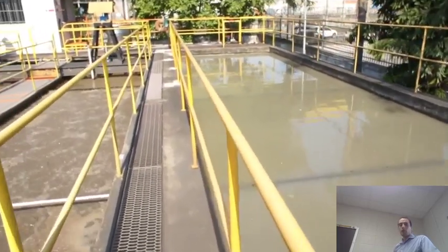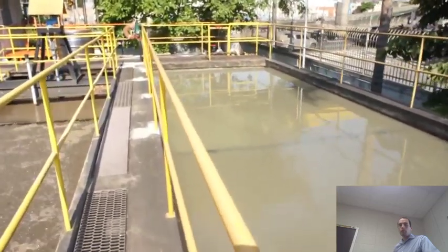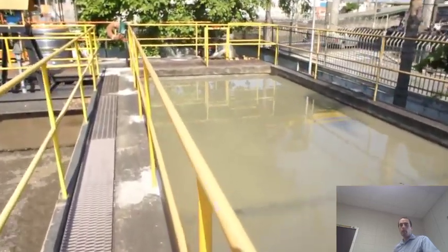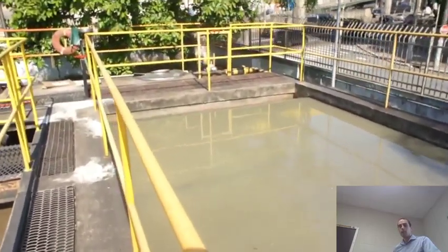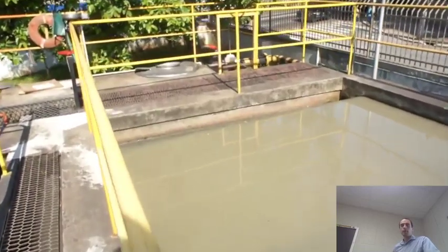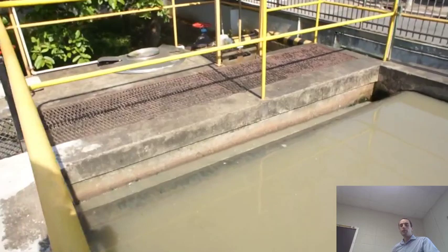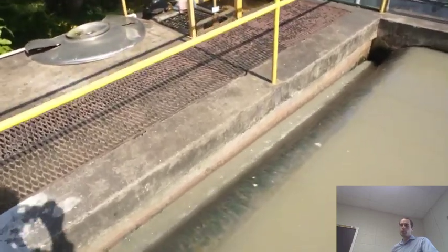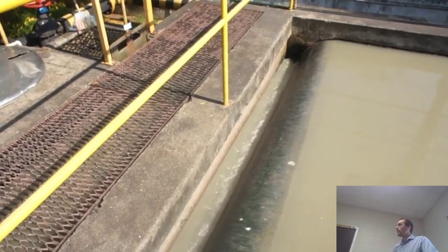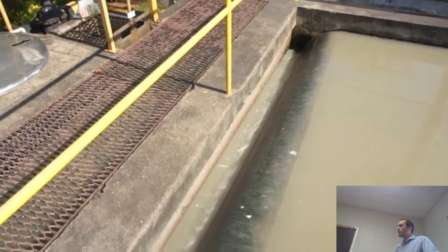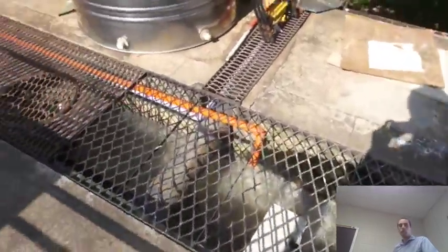I could be wrong, and that could also be some sort of an anaerobic, or not anaerobic, but anoxic process, so they're not adding oxygen to it, on the right there. Saw briefly on the left, they'll walk by it again in a moment. Another basin. I think on the right here, this is a clarifier of some sort, because it's collecting the water over the top right there. So that might be the primary sedimentation. It's just doing a first rough draft. Water is, of course, pretty dirty still.